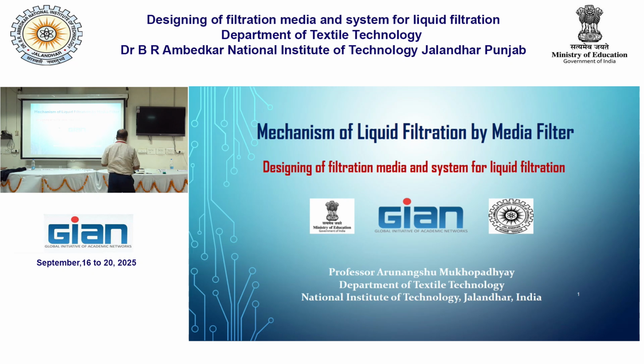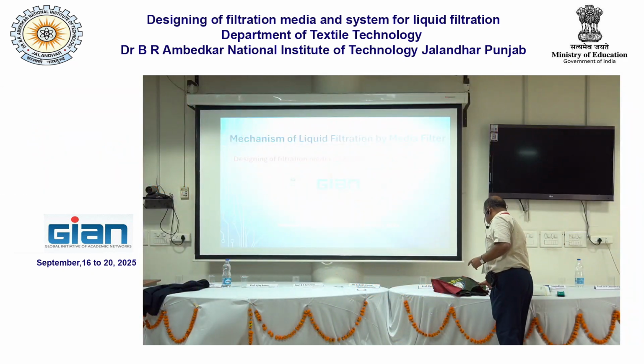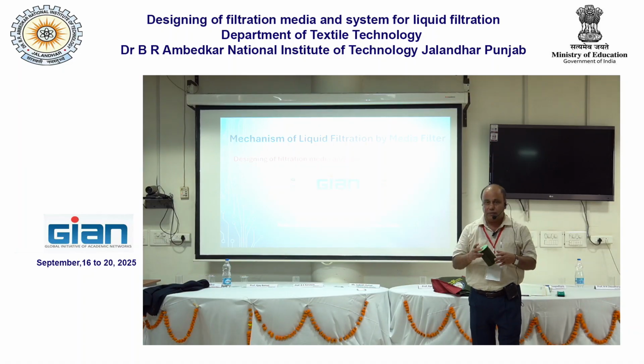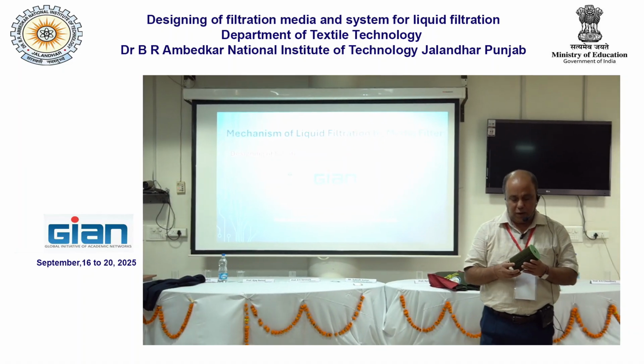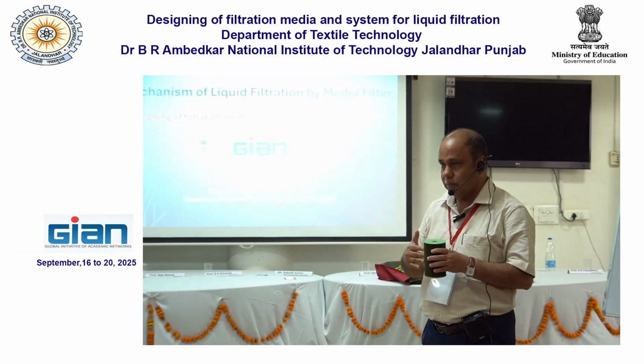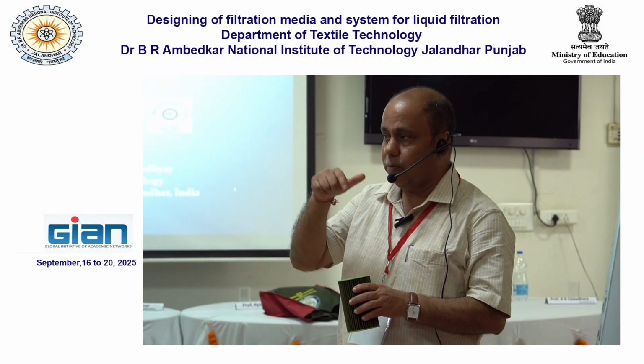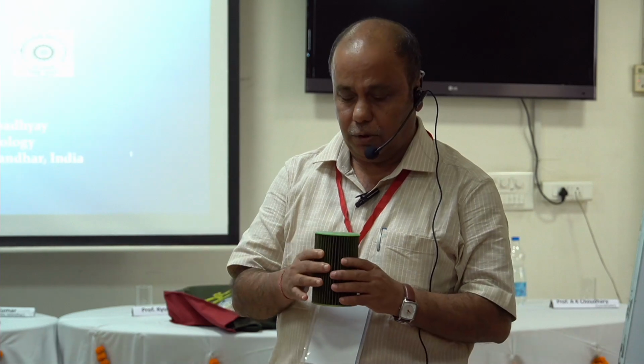Now before I proceed, I would like to show some of the materials used for liquid filtration applications. So this is the engine oil filtration. Oil comes from the outer side, and the clean oil moves from the inner side to the engine. Here it is a cartridge. It is known as a cartridge because it is one system, one housing, which can be fitted very easily in a system. And why is it split? Splitting is done because you can get a larger surface area in a given space. That is the primary reason for the splitting.